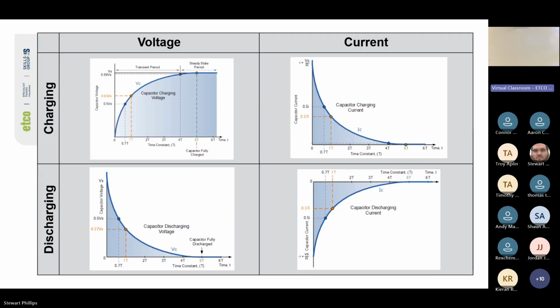If you see the charging, the voltage reading across the capacitor goes up and up and up. It stores that charge as a voltage. Remember, voltage is a measure of potential difference. So the more voltage in the capacitor, the greater the potential between the capacitor and ground or earth. But as we increase the voltage, current flow drops off because it's reaching full charge or full saturation, whatever you want to call it. As you can see with the discharge, it's the opposite.